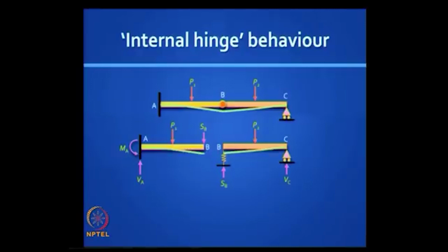BC is dependent on AB. For example, the load P1 acting on that structure will go entirely to AB because AB can stand on its own, nothing gets transmitted to the support at C, but the load P2 needs the help of AB, so part of it reaches AB.